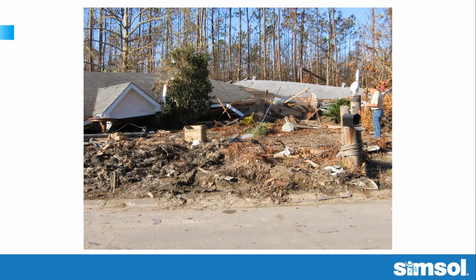Let's take a look at this one and see what we see. Again, your trees are looking pretty good, but take a look at the house roof that's crumbled, laying on the ground to the left. Notice that most of the shingles are intact. The siding on the gable end that's exposed is intact. All of our fascia that we can see, with the exception of a little bit at the right end, is intact. We have a little bit of shingle damage at the right corner there.